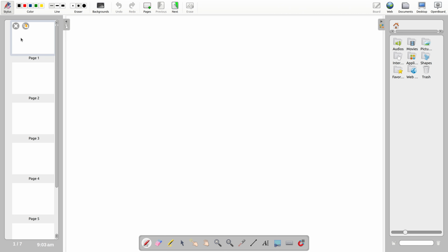Okay, so we should also note that this mass matrix we can also lump and make it into a matrix which just has diagonal elements, and then we could also just take a constant value out, and that would be a lumped approach. But here we are looking at a full mass matrix approach, so that is why we are just writing down this mass matrix. All right, so that is your third step.